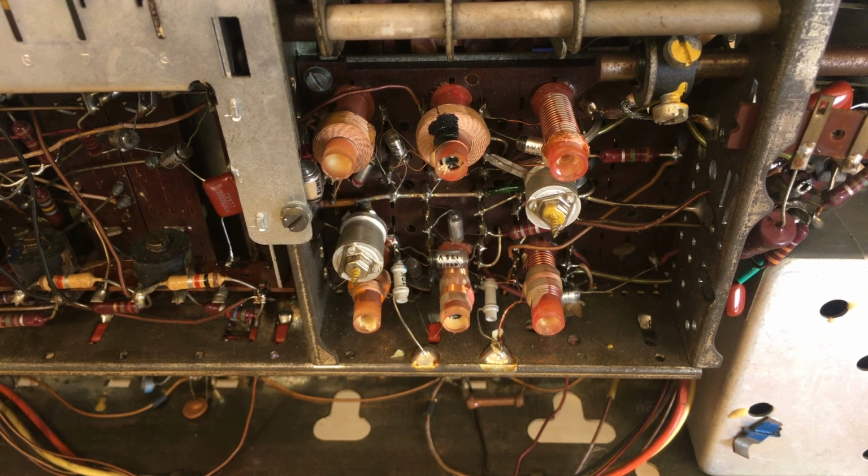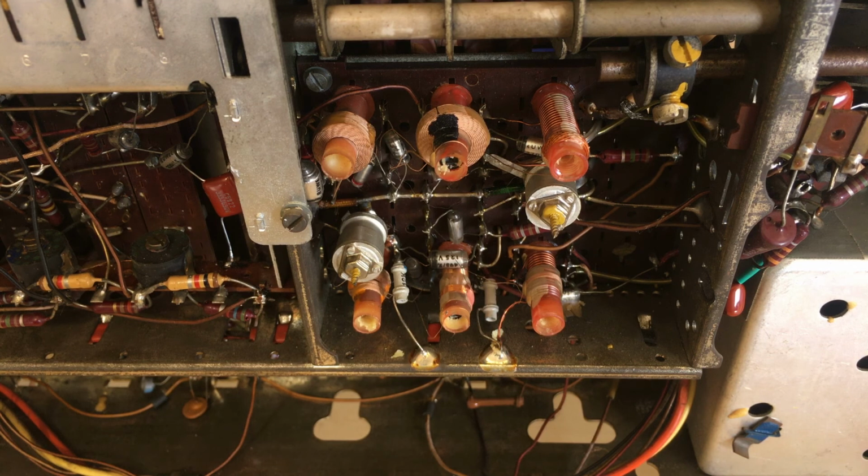The reason you want that is you don't want outside IF frequency coming in and messing up the one that you're trying to create inside. So that should cut out 460 kilohertz. And I'm not going to mess with that because I don't hear any tone at all. You hear noise, a lot of noise, but no tone. So I think that one's set well.